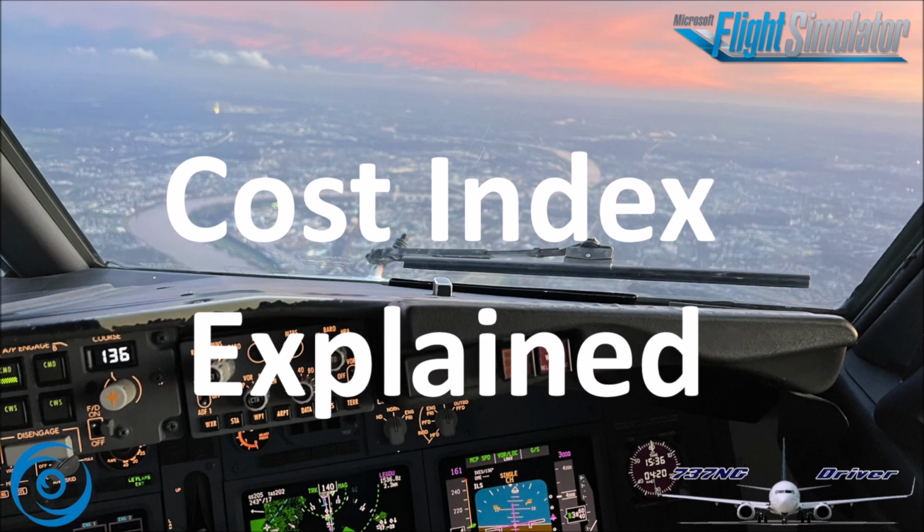So, in general, ranges of allowable cost indexes for Boeing airplanes are usually between 0 to 999 or 0 to 9999. At least for the 747, 757, 767 and 777, while of course in the 737 things had to be made a little bit more complicated. So in the 737 Classic we're looking at a range of 0 to 200, and in the 737 NGs we're looking at 0 to 500.